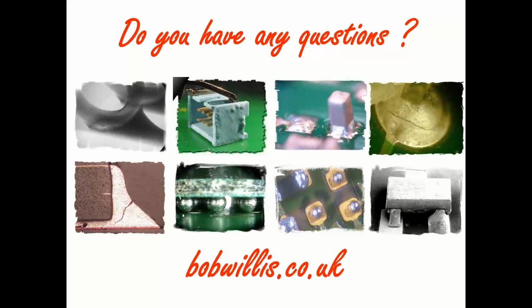Do you have experience with rubber conformal coating? Okay. No, I've only used rubber coatings on one automotive product in Germany, and it was a pretty simple process, in all honesty. I can't remember the supplier, but it was coated. It's an inline curing process. So a tent, you went up to whatever the temperature was, I think it was 90 something degrees C. You stayed there for about 3 minutes, then came down, something like that. Very simple process. And it was that performance they required for that particular product.